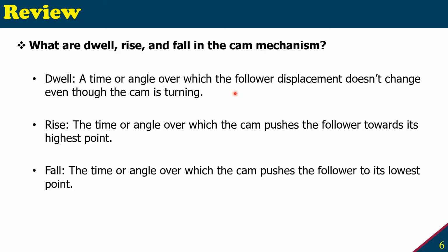And while it is doing that, there will be a position where the cam is rotating, but the follower is not having a displacement. That is the dwell time. And we'll see examples really soon. Then comes the rise. It is the time period or angle over which the cam pushes the follower. So again, the displacement, the time over which the cam is pushing the follower, is the rise.